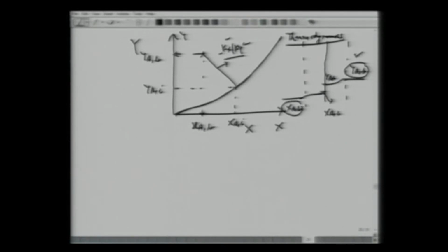What we know is possibly the bulk concentration, because we can measure that sulfur dioxide is 1% and how much is the water concentration of sulfur dioxide. So we know this point here. Now if we know the operating conditions, say the Reynolds number and the Schmidt number in the gas and liquid phase, we can calculate kx and we can calculate ky.